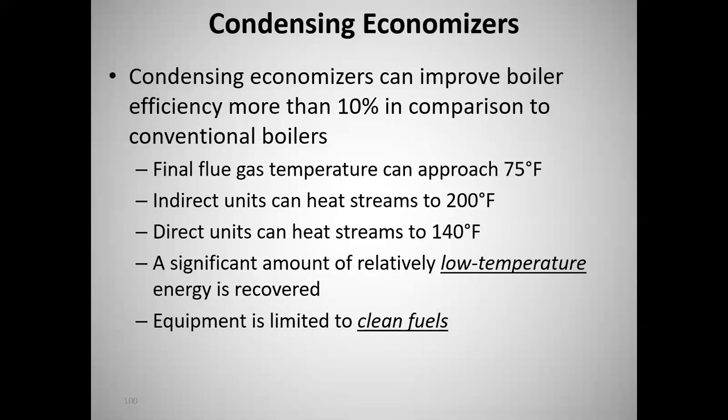Okay, so think about it. In general, I've got this big flow of combustion gases at, say, 250 degrees, and I want to cool it down to, say, 100. So what else do I have to have? I have to have something cold that I want to heat up, right? I can't cool these gases to 100 if I don't have another fluid, a gas or liquid, that's, I don't know, 75, 80, 90 degrees, right? Because how are you going to get that leaving gas temperature out of this condensing economizer to be as cold as 100 if you don't have something colder than that to put into it? Well, that's the rub. Lots of plants, lots of businesses, lots of different manufacturing concerns don't have anything cold enough that they want to heat up.